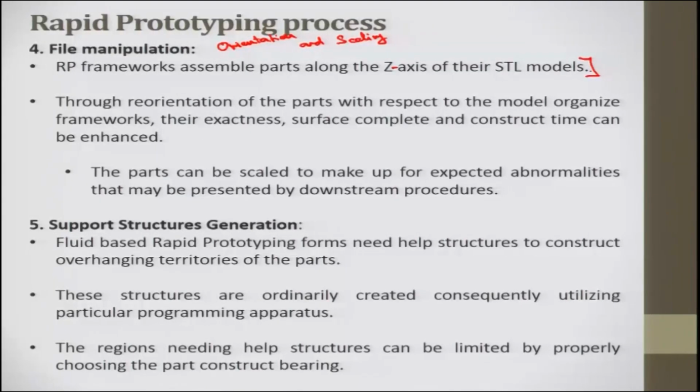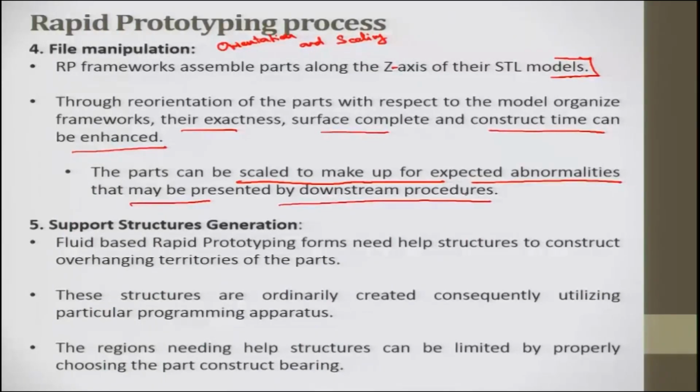According to that, the best orientation is set so that minimum time is consumed. Through reorientation of the parts with respect to the model, the frameworks' accuracy, surface finish and build time can be enhanced. These parts can be scaled also to make up for expected abnormalities that may be introduced by downstream procedures.